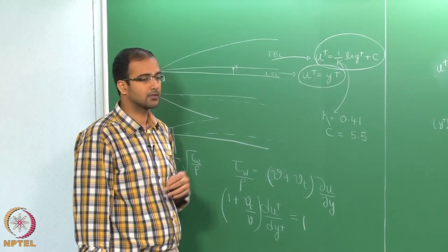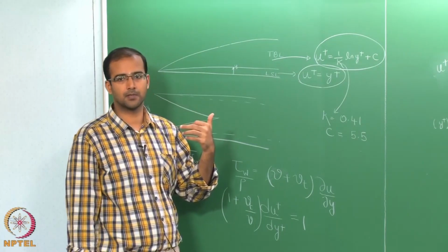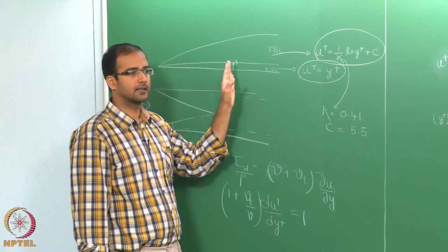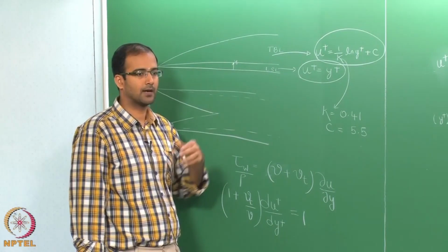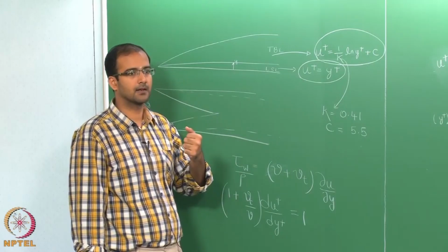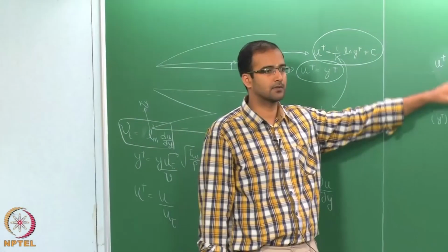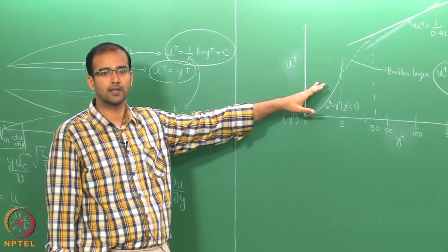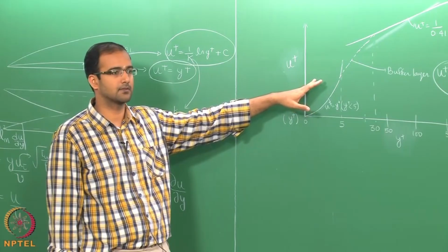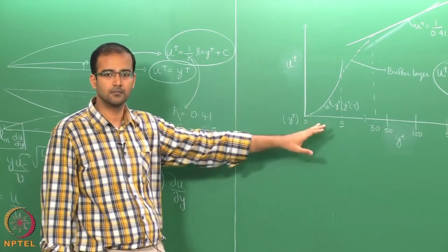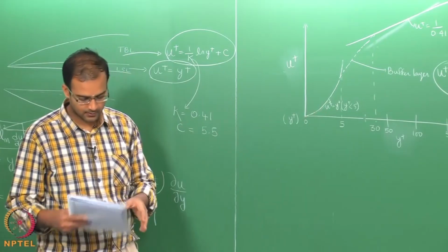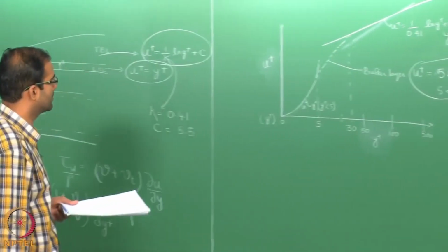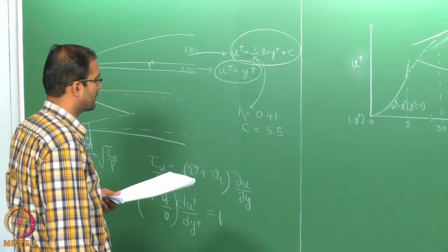Okay. And also this has to make sure you do not have any adverse pressure gradients. This is derived for the case of a flat plate boundary layer. What happens if you have a favorable or adverse pressure gradient? Again those pressure gradients will change the nature of these profiles. So, then you have to do an experiment and find out how these profiles vary and then plot them. So, this is the basic idea about the variation of velocity profiles.